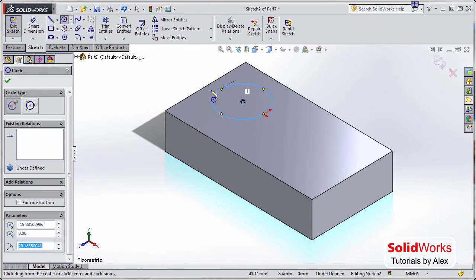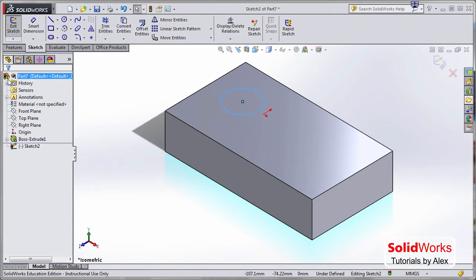So when you create a circle, you can control the radius by using the arrow keys here, or you can type it in here. Let's just say 10 radius or 15. Let's make this 15 here. Hit enter. So now when you're okay with that position, just click on check here. Make it a habit: check, and then exit sketch.